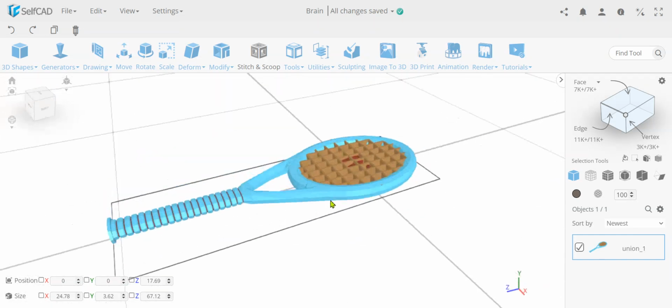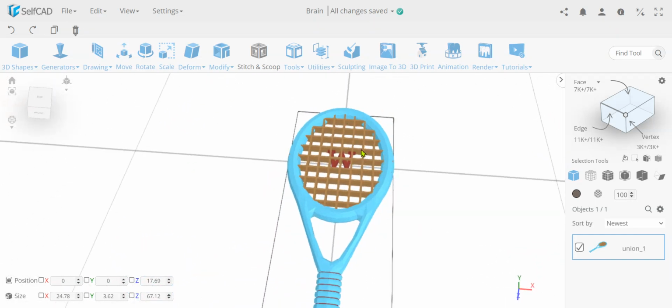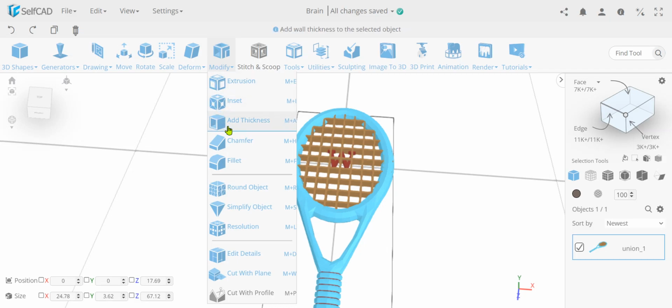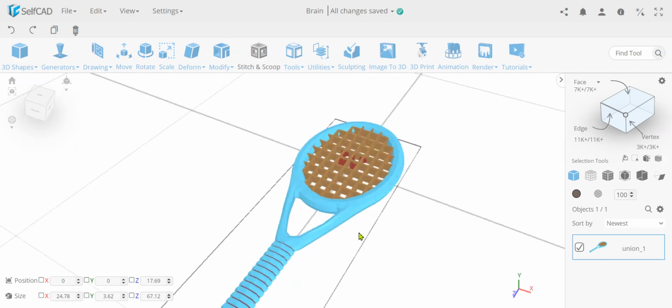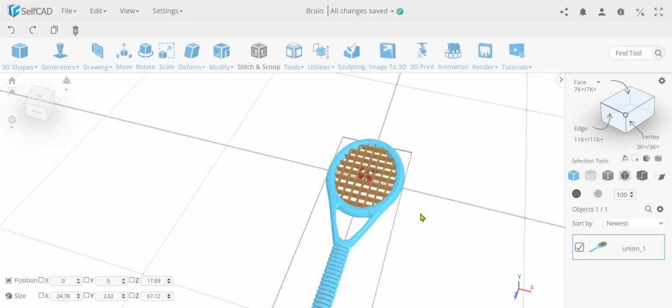And then finally we added over here another cylinder, another plane to create the grid using a fillet with the option to remove the inside polygons. And then we used a cylinder to cut out the section using the intersection option. We added the text, we added colors, and then we simply combined everything.